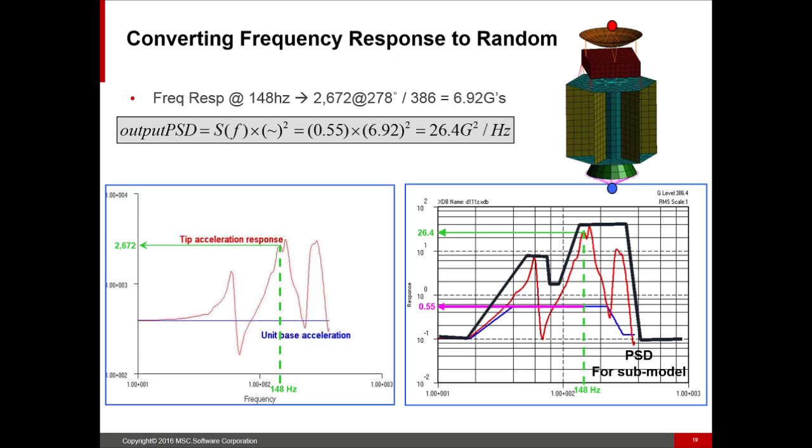The other part here, a very practical aspect, depends on how closely we calculate that output based on what we found from the larger part of the structure. That is the output PSD, but we can also refine what that response is. This is where sometimes we are asked to go back and say, well, can you get a few more modes, take a look at certain sections in a little more detail, and sharpen up our pencils on what the input PSD will be to another part of the structure. So that's part of how we assess and how we pass this information on.